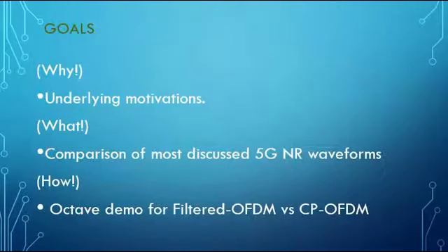Goals of this presentation are listed here. First of all, we want to understand the underlying motivations for understanding various waveforms. Then we will compare various waveforms which are discussed for 5G new radio, and in the end, in particular, we will compare the filtered OFDM with the cyclic prefix OFDM.